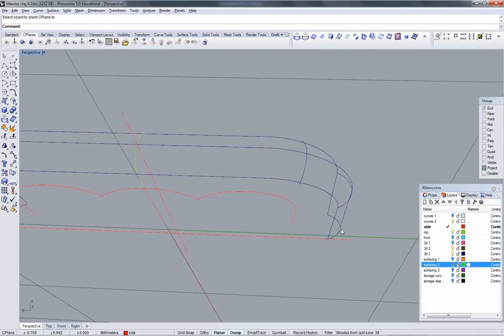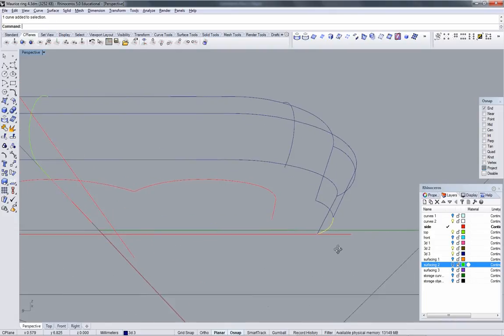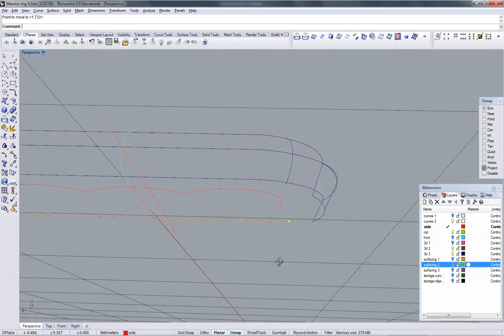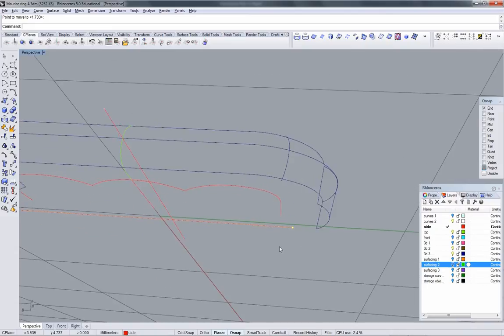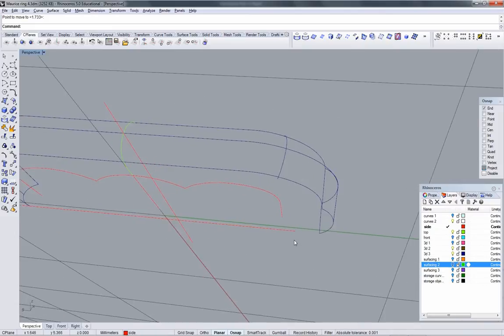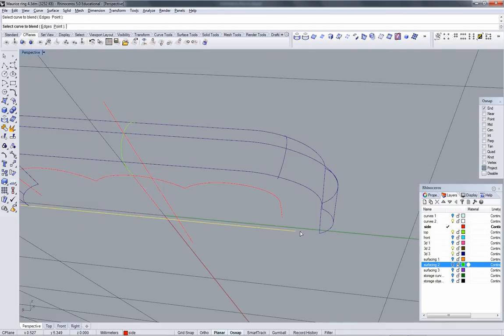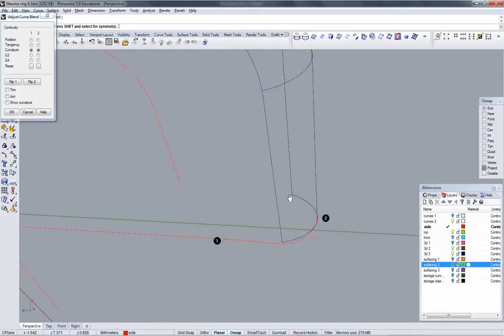It's going to be the same idea. I'm going to split this. Just going to turn on the control points here, F10, and then move this control point back. I want it to be beyond where this is at. That's fine. And I'm going to do a blend surface between those two. I obviously don't want the bubble hanging out the end.